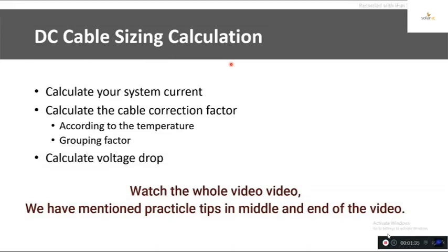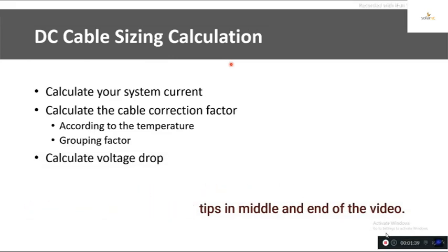I would like to tell you the steps to follow. First, we need to calculate the maximum current of our particular system, so we'll come to know what will be the maximum current flowing through our cable. Next, you need to calculate the cable correction factor.